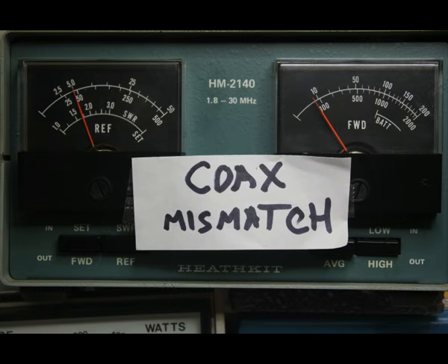And let's look again. Remember that little trick I told you about, subtracting the reflected power from the forward power to get the real power, because the meter is now in a totally wrong impedance, and the voltages and currents in the meter are just way off from what they should be. So let's do that little trick. We see we have something less than 100 watts. This meter's not going to be real accurate, because we're way down at 100 watts on the 2000 watt scale, and the meter's pretty far out of correct termination.